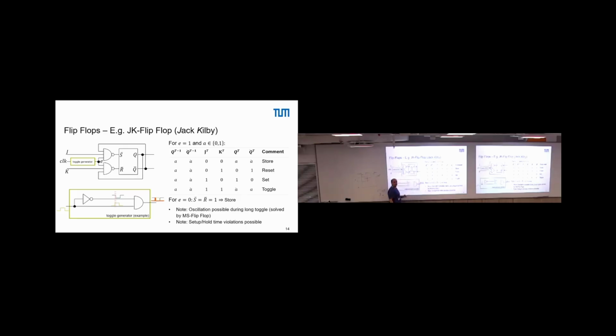So why should this be better? Well, we can now make the time where we can switch this flip-flop, at least virtually, very small, very short. This idea at least existed. If we make this short enough, then the bit will change, but it changes only one time, so it toggles the bit, and then we are done. And then if the feedback arrives, this high signal is already gone, and we are safe so far.